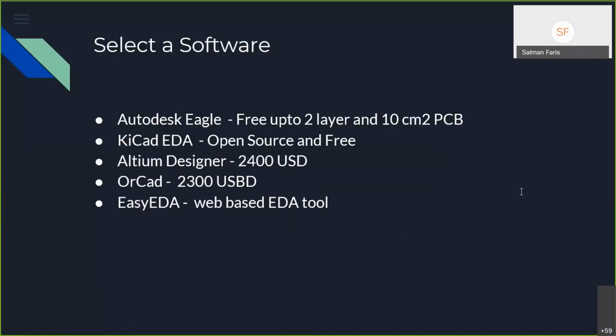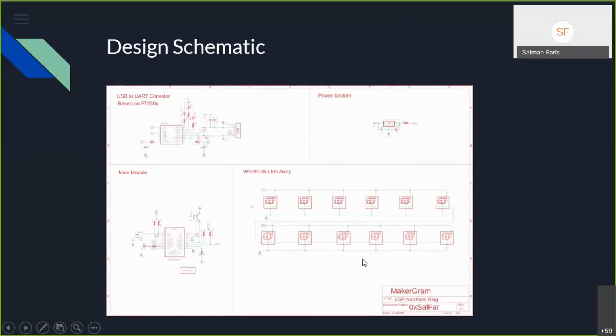So what is the difference between design schematics and design board layout? Okay, that's a good question. Schematics are only for the logical relation. Here we are only connecting this pin to connect here, and this pin connects here. That's all. We are not making the actual PCB. We are just connecting the components. It's like initializing variables in programming.